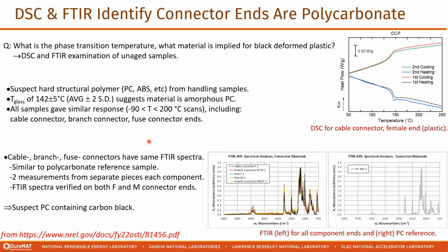We also compared the same samples in FTIR, and I had a reference polycarbonate sample. We took 2 replicate measurements from each of the samples, and then looked at both ends of the connectors. And so what we're saying here is that we think that black plastic in these components always consists of polycarbonate, most likely stabilized with carbon black.